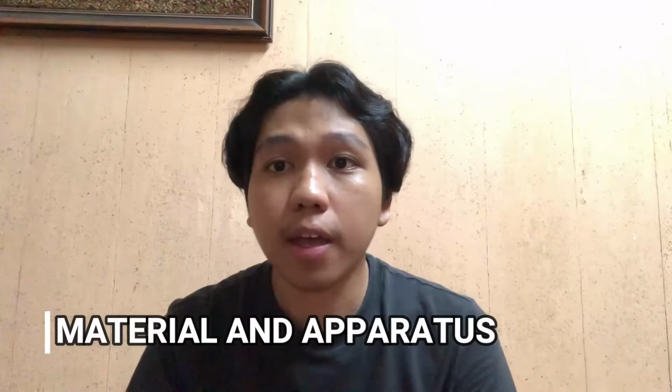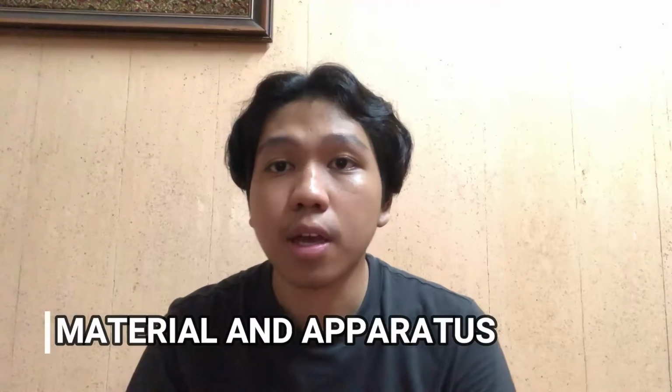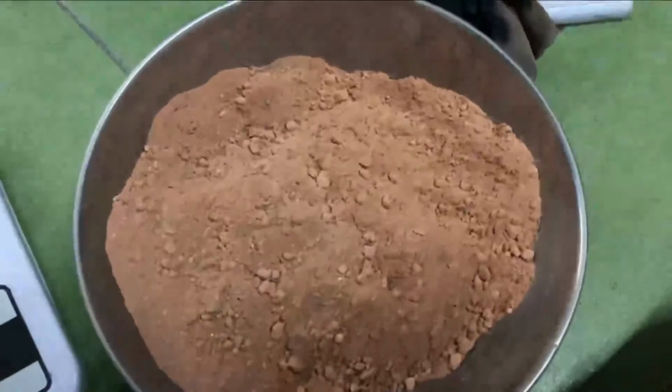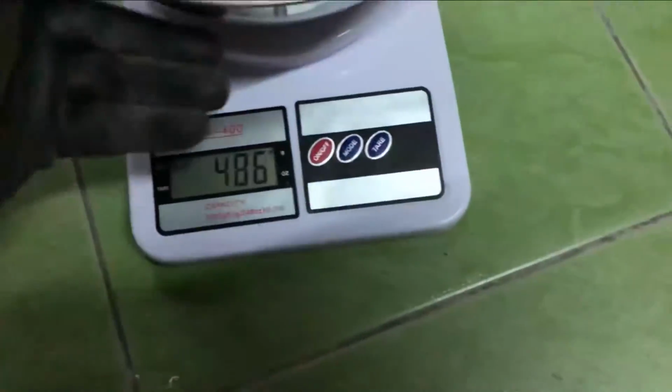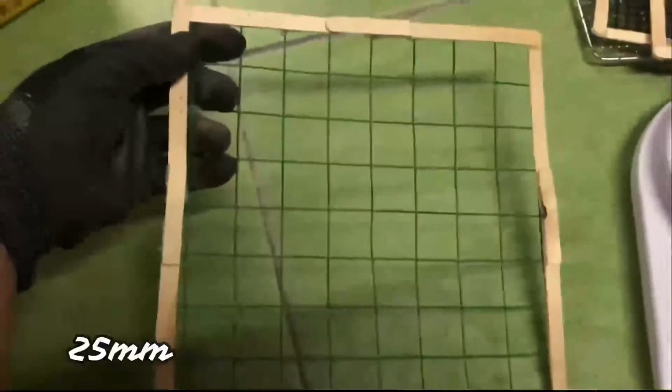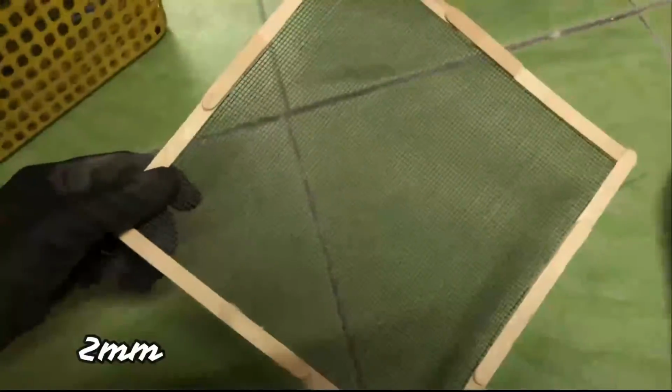So the apparatus and material that I use in this experiment is 25mm sieve, 15mm sieve, 5mm sieve, and 2mm sieve. I also use digital scale, a tray, and a metal bowl. First of all, I use about 1000 grams of dry soil. So this is 25mm sieve, 15mm sieve, 5mm sieve, and 2mm sieve.